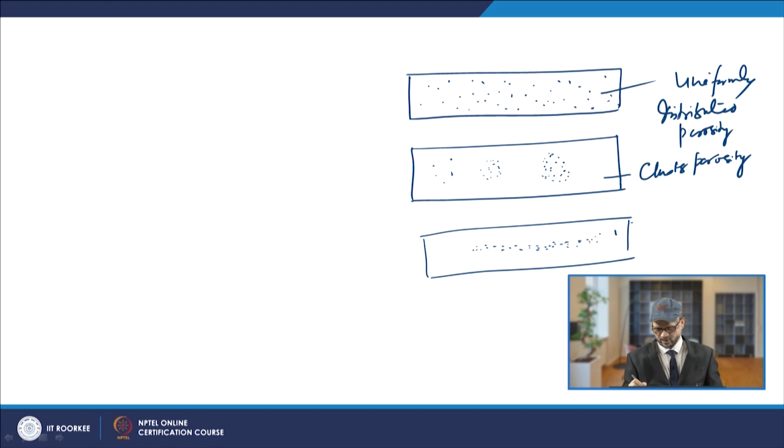That way, it is normally because of the excessive moisture in the electrode covering. Because of that you will have this kind of porosity, which is basically known as linear porosity. This is the example of linear porosity.